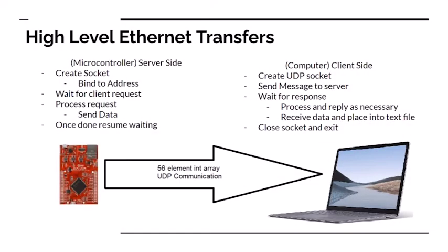Now that data has been processed by the microcontroller, it needs to be sent to a computer so that it can be analyzed. This is accomplished using an Ethernet cable. The microcontroller packages the data that needs to be sent to the computer. It then connects to the computer by sending a communication request. Once the computer sends back an acknowledgement, data begins to flow from the microcontroller to the computer. A program on the computer side then sends the data to a file that will be used when we analyze the data.